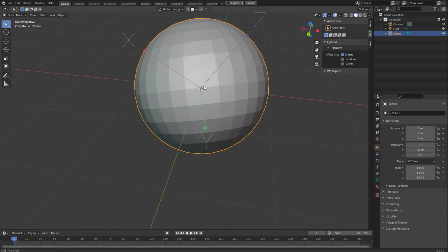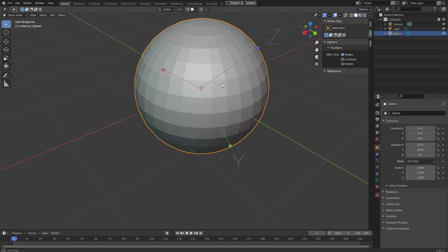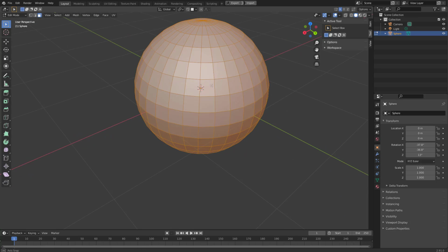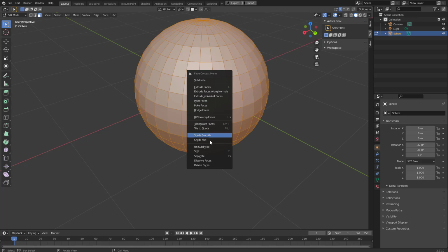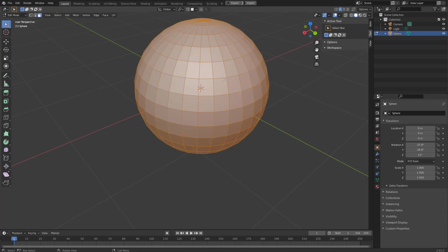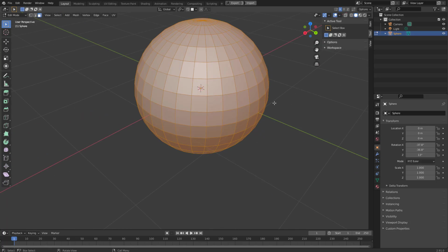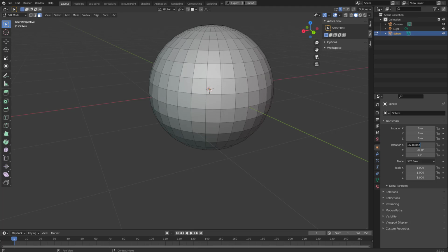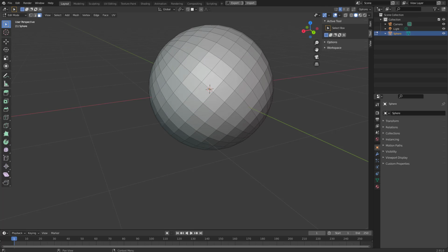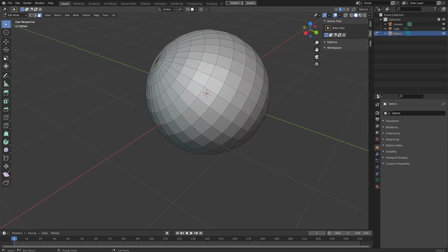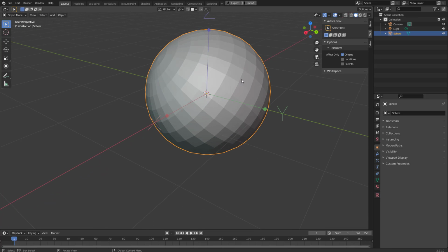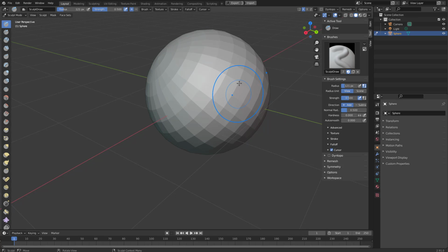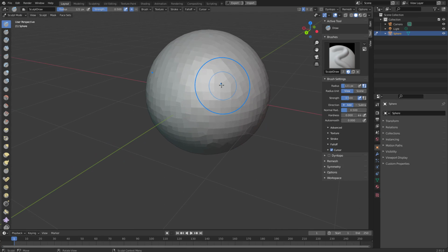let me go back. How about this? We go to edit mode and hit A to select all and right click. No, can't do that. Okay, well, I'm gonna do this then. I'm gonna go for the zero out all the rotations. Okay, and I don't need to have this exact topology, so I'm gonna go to sculpting mode and then Control R to dynamesh it.